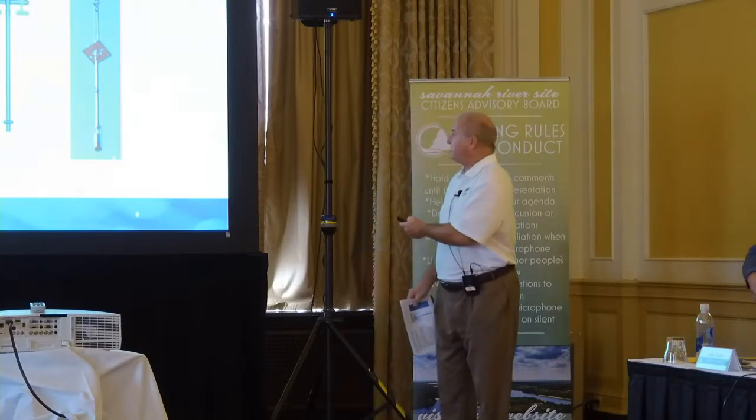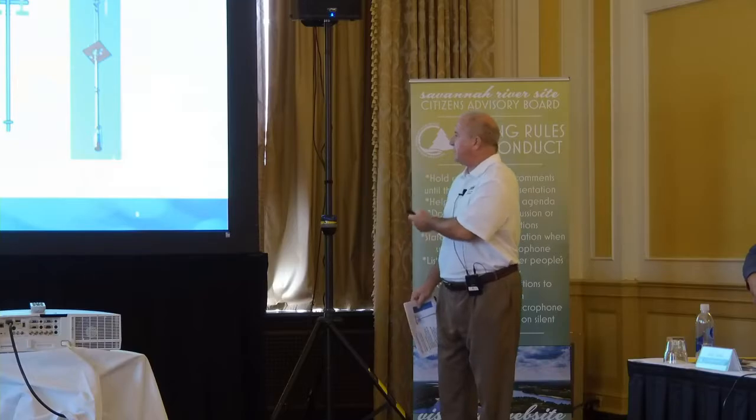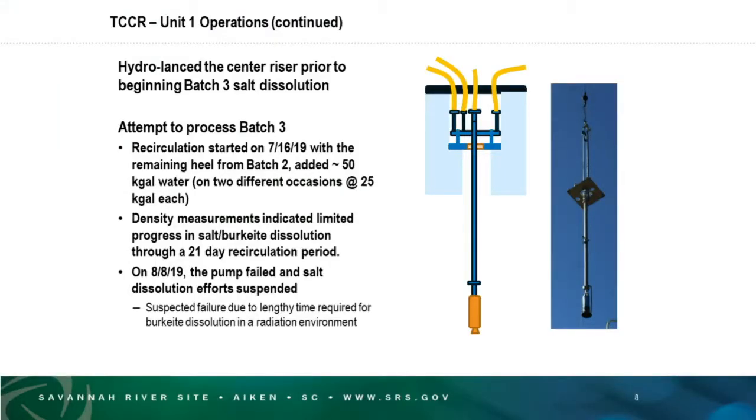The picture that you see on the right-hand side here is the actual transfer pump at the bottom of a mast with a plate that immerses in the riser. It's kind of hard to see here, but this indicates what a riser looks like, this being inside the tank right here. And that ledge that you see right there is this ledge. It sits on the ledge inside the riser.